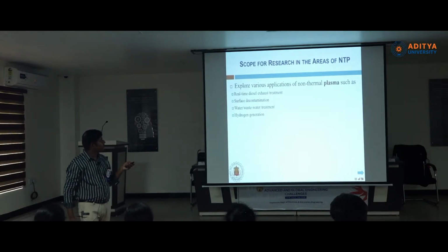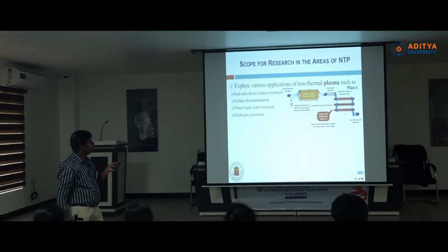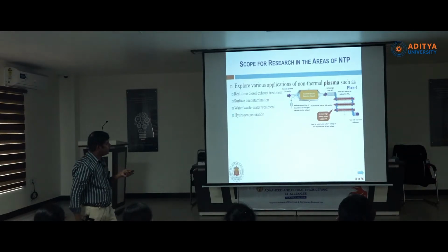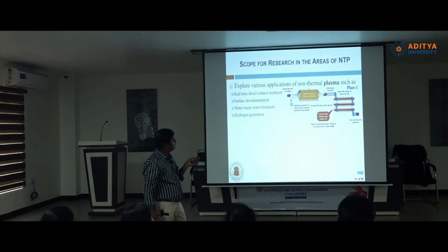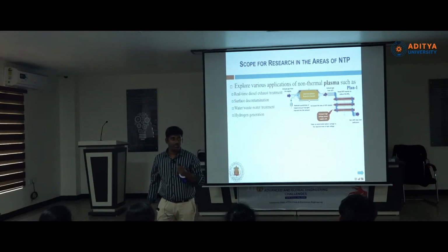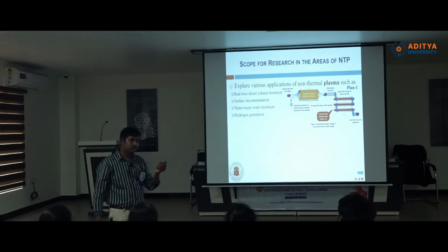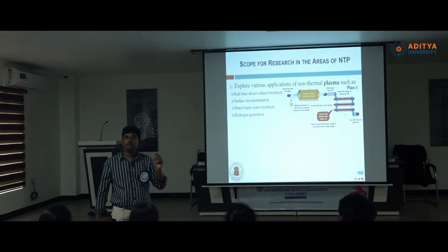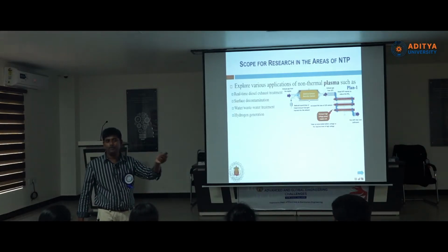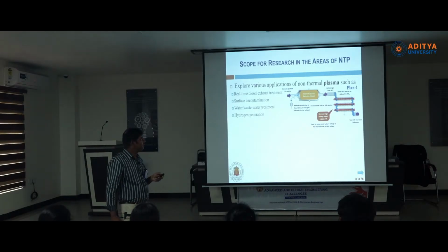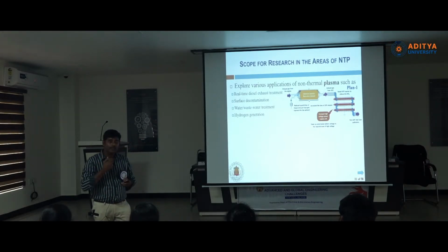Then surface decontamination, and real time diesel exhaust treatment. You can see selective catalytic reduction is the technique which we are using currently. A catalyst will be used to control the NOx. You might have heard the norms, they become stringent day by day. NOx emission needs to be controlled, it is almost zero now. In the latest BS6 norms, a diesel vehicle should not release any NOx, 0.0 ppm or some small ppm. So to that extent, if one has to control it, people are like